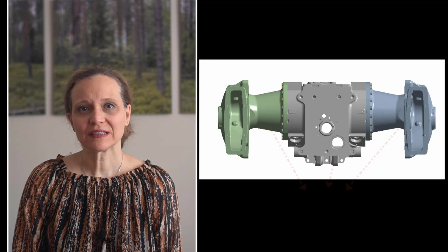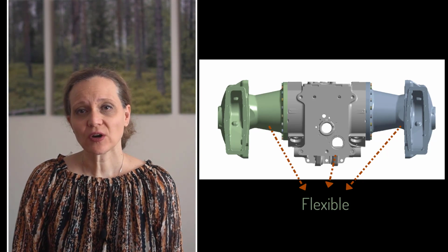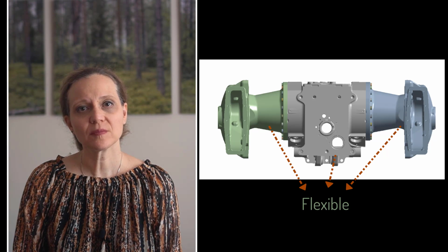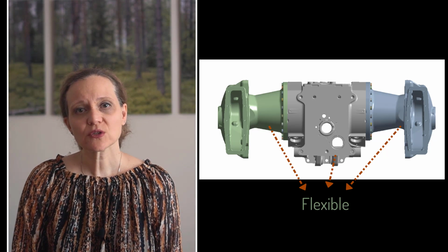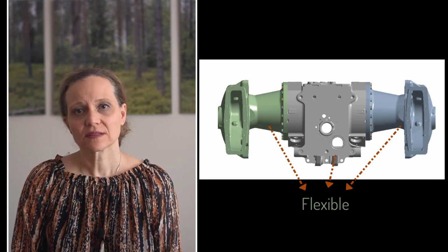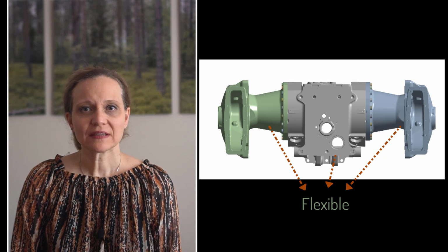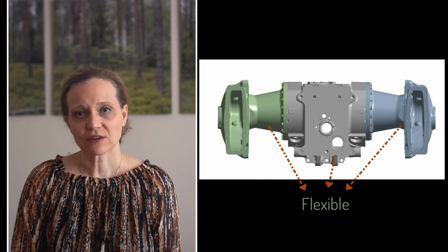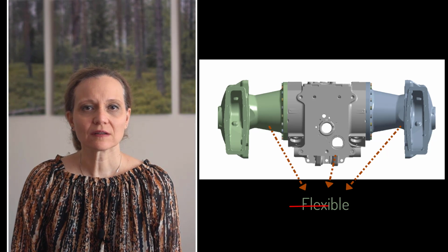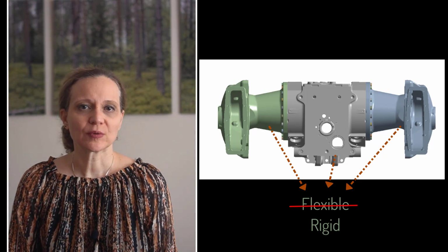Typically, we would model the 3 parts of the enclosure as flexible, as the flexibility of the parts can affect the load path of the force and how the bolts will carry the load. Also, we would usually include the preload of the bolts, but we have not discussed the topic yet. So to get acclimated with the Mechanical user interface and to learn some productive tips, we'll treat the 3 large parts as rigid to simplify matters and to reduce the computational time.